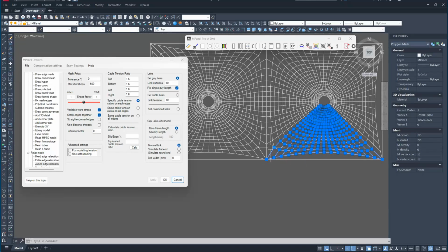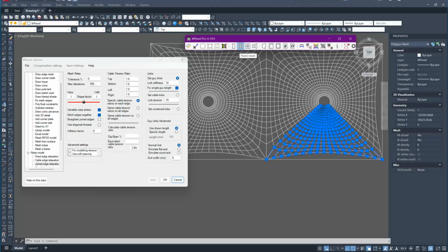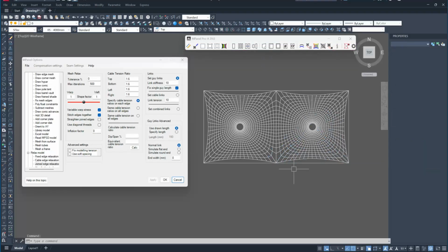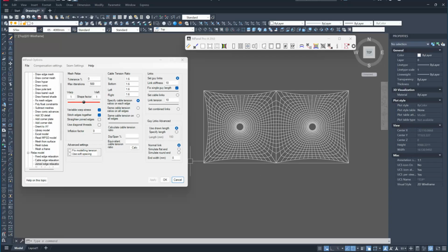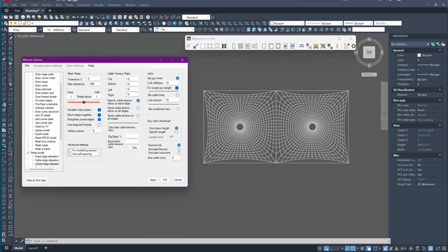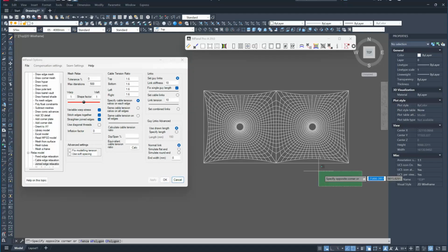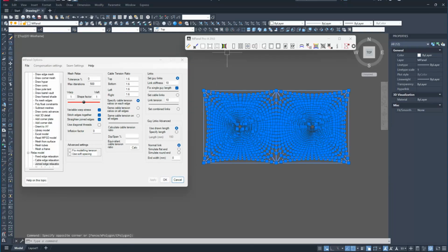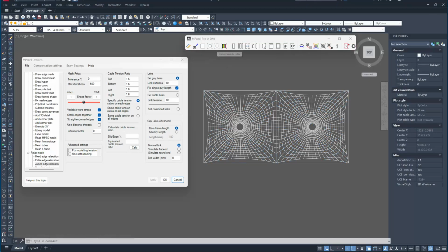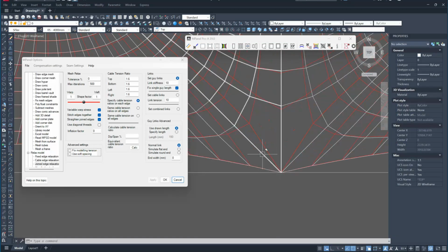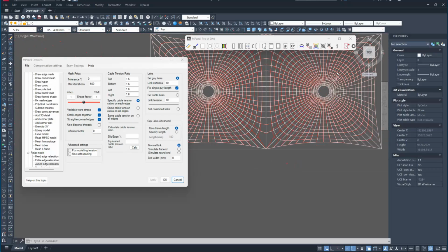However, this edge is not ideal as a seam edge, which prevents us using the simple tool to panel a complete mesh to split this up into multiple panels because we'd end up with undesirable seam edges. So a new tool was introduced into MPanel to straighten joined edges. So if we select this tool, apply, select everything, and relax again, and we can see now these edges are now completely straight.